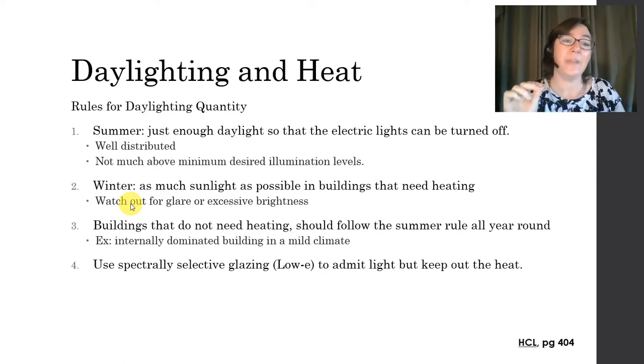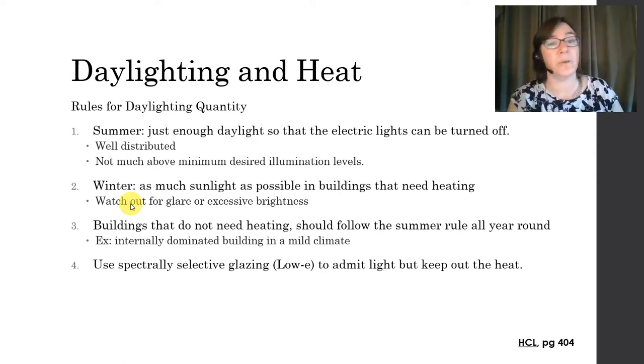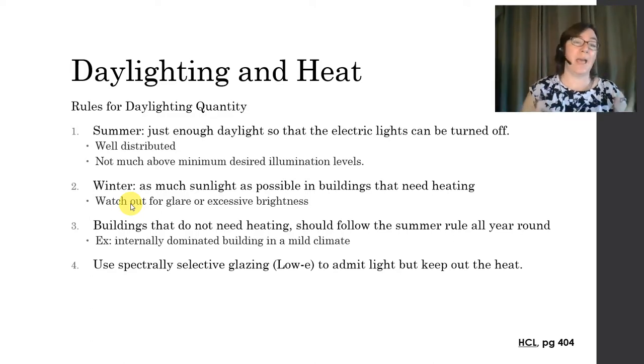There is a little caveat there. There are some buildings that don't need heating. They are internally load dominated, in that the activities inside the building actually produce as much heat as that building needs. Often these buildings are located in mild climates, so they didn't much need heating in the first place. If you've got a building like that, follow the summer rule all year round.